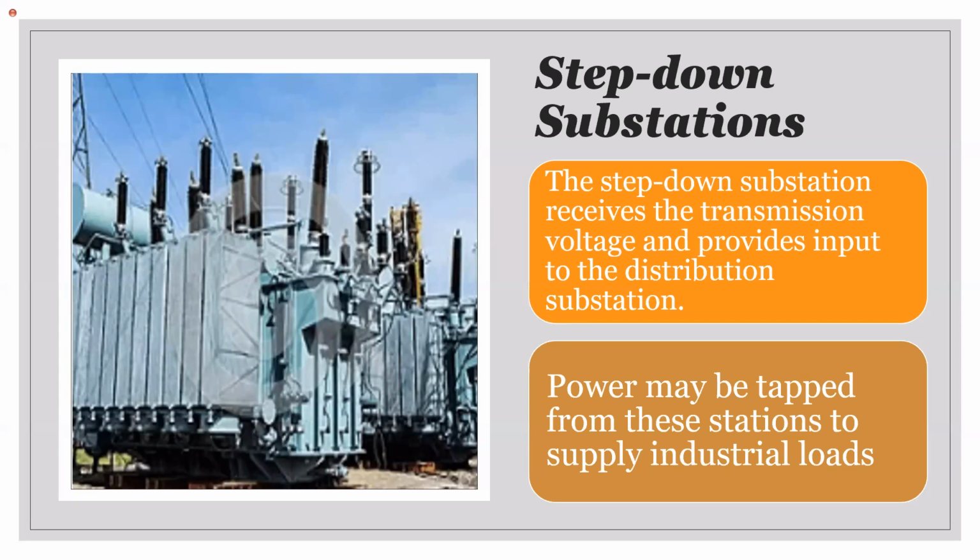So what we are saying here is that for industrial facilities, in a jurisdiction such as the UK, they may take the 132 kilovolts. All right. In Jamaica, for a large facility, and I mentioned earlier that there's a dedicated feeder going into the flour mills, they will take 24 kilovolts. All right.